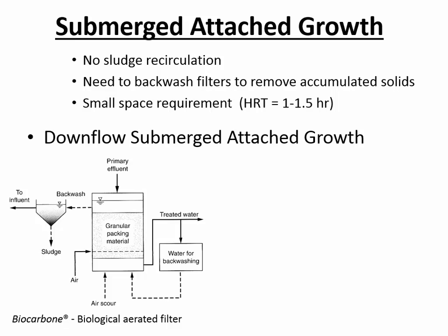Here it's a similar kind of effect in that you've got submerged attached growth, and the growth of the bacteria is on a packing material, but it's fully submerged inside of a tank, and it's going to need to be cleaned off occasionally because of sloughing.